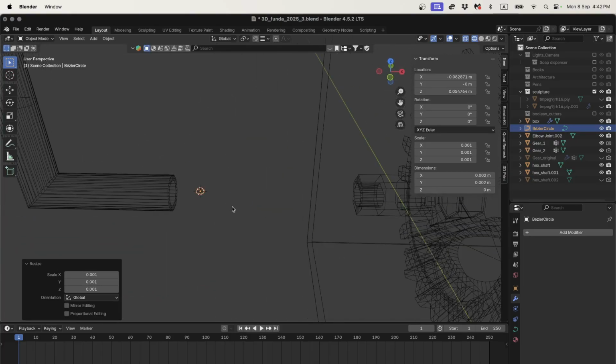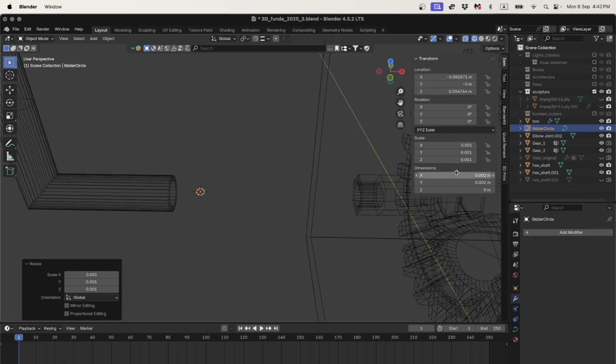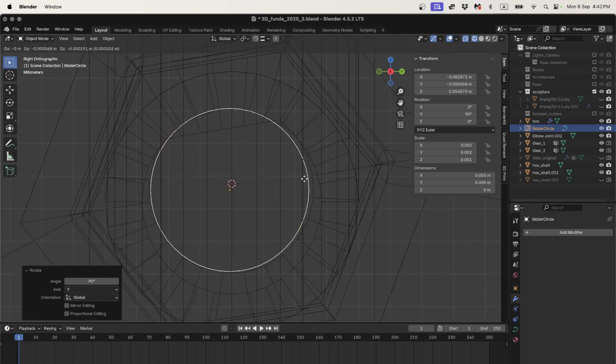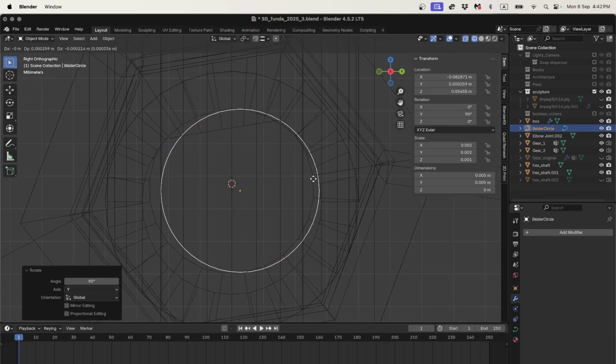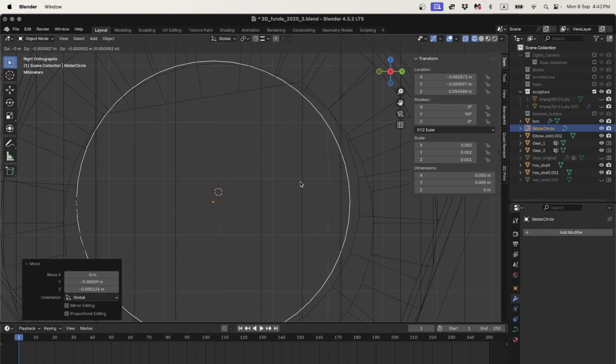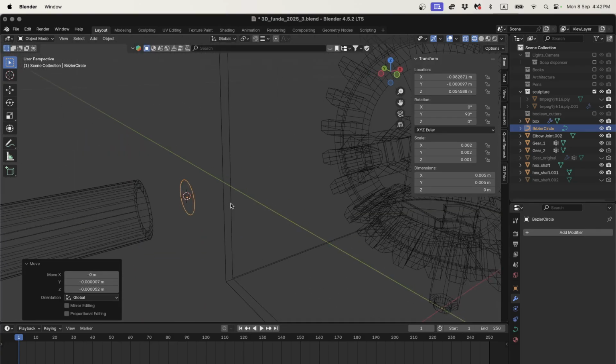There it is, it's a bit small, but I'll make its size here 0.005, nice, and I'll rotate it on the y-axis RY90, and I'm just going to look down my x-axis, and it's going to be exactly where we want our D shaft to be. It's a little bit imprecise.